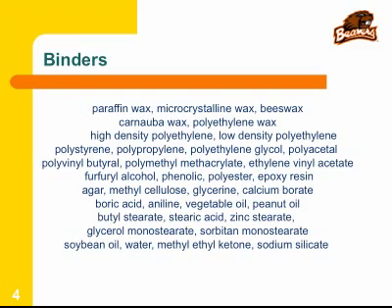Okay. So here what you have earlier on, the different kinds of waxes are relatively lower molecular weight materials. They are solids at room temperature, but at relatively low temperature, between 40 to 60 degrees centigrade, sometimes closer to 80 or 90, many of them will completely melt. Then you go down to a lot of different thermoplastic materials over here. And so in that case, you have to deal with materials that you can heat and cool cyclically without a problem.